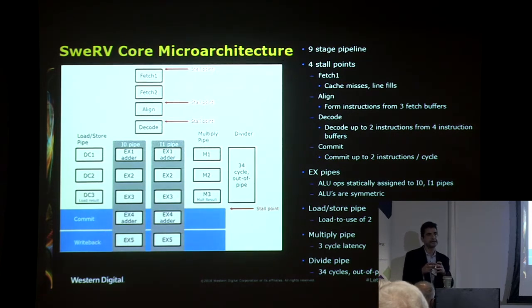When that happens, if the subsequent flow of instructions after the missed load does not refer to the registers that participate in the load, the core will continue executing and do the scoreboarding in hardware in real time, and only when that register gets referenced will it stall. So we allow that little bit of out-of-order execution. It helps in those corner cases. It helps a lot. It also allows firmware programmers to be aware of it and write the code in a different way. Thank you. My pleasure.